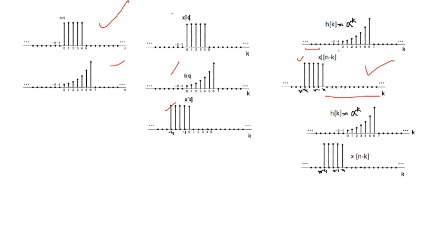So if you multiply these, although at some instances this signal is non-zero, the input signal is 0, so the product will result into 0. That means there is no non-zero overlap here, so the convolution here will be 0 and the output will be 0, and this continues, you see.